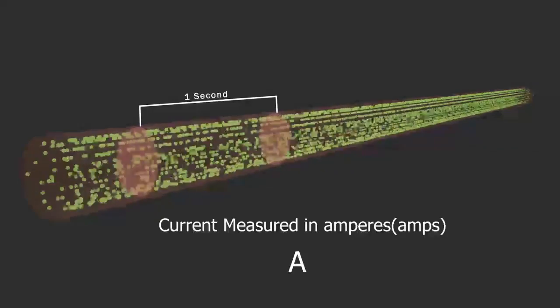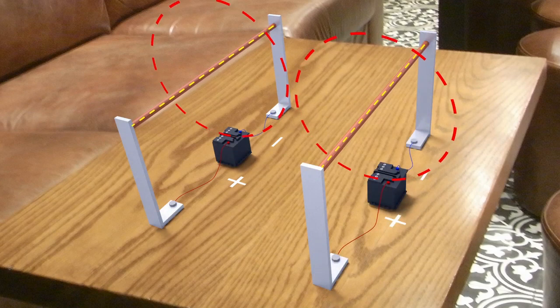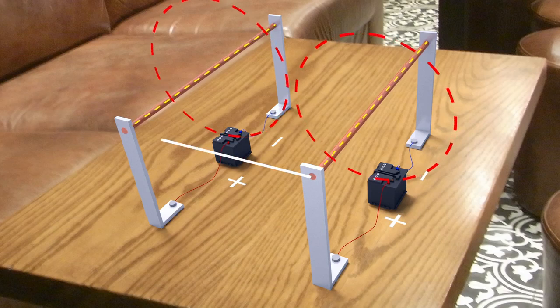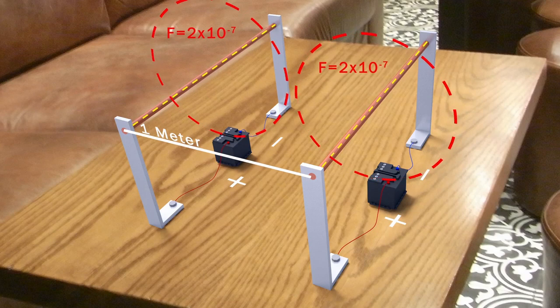A current of 1 amp means that current passes through a cross-section of two conductors, which are placed in parallel 1 meter apart, with 2 times 10 to the power of -7 newton per meter of force occurring in each conductor. It can also mean a charge of one coulomb, or 6.24 times 10 to the power of 18 electrons, passing through a cross-section of a conductor in 1 second.